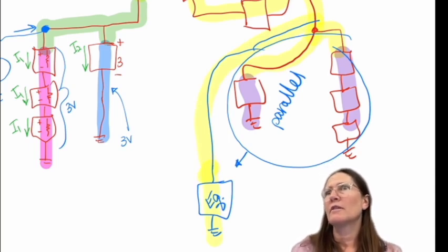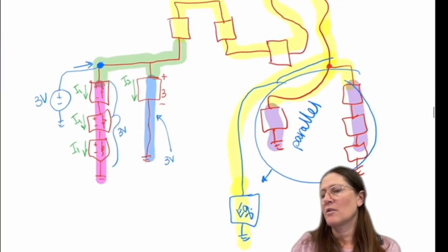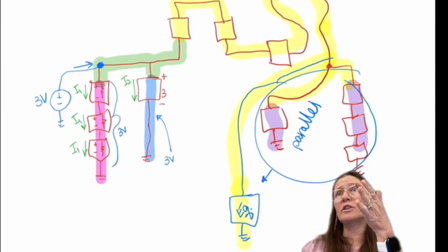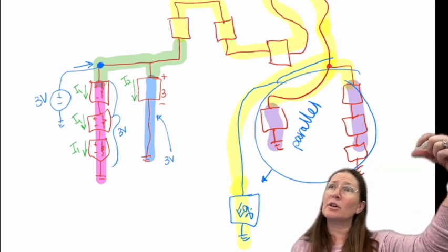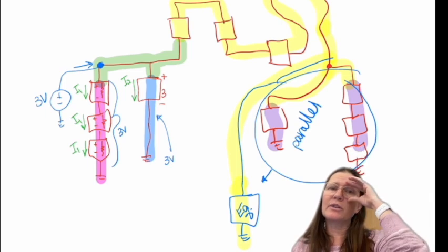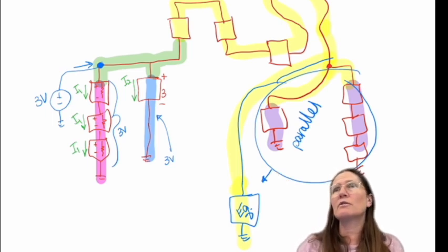And then would you make another equivalent between all the other resistors and then find the voltage across the total? Correct. So if they were all resistors, I could just join those, like the 3 on the left would become 1 as in series. That would be in parallel with the second branch. And then this third branch would be those 3 in series at the top, 2 in parallel for 1, and then add them all together once you formed them into parallel.